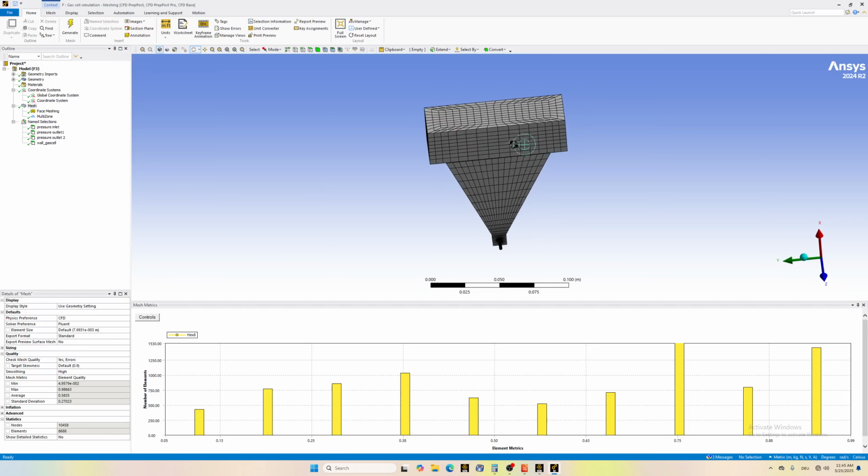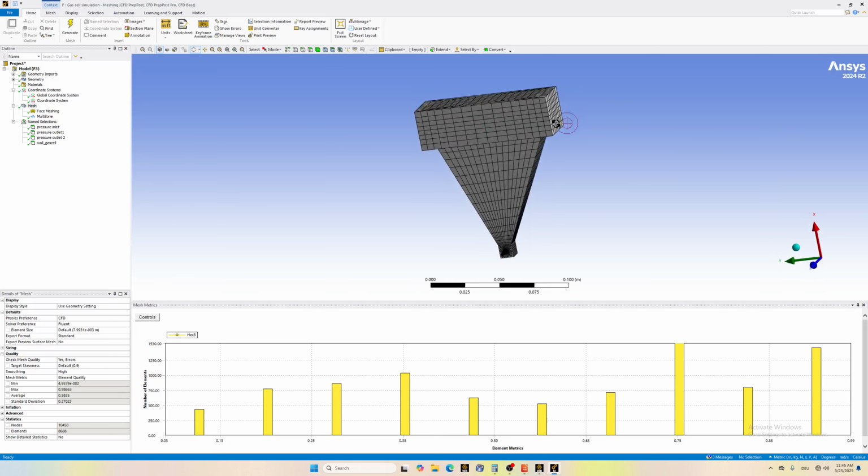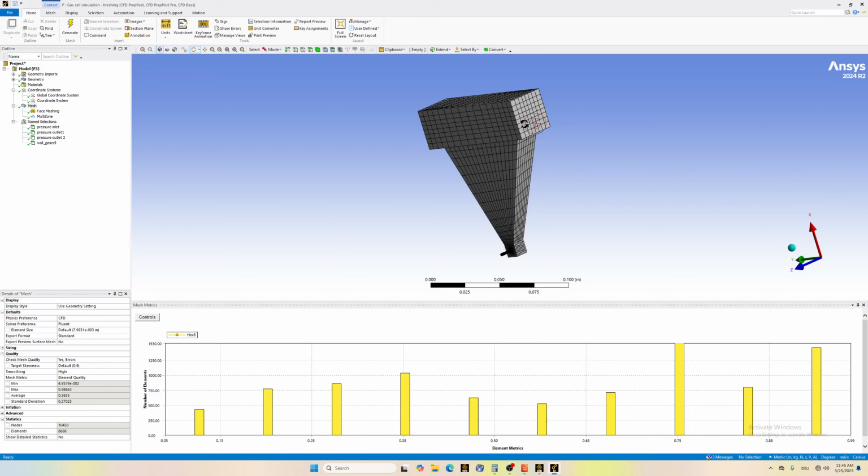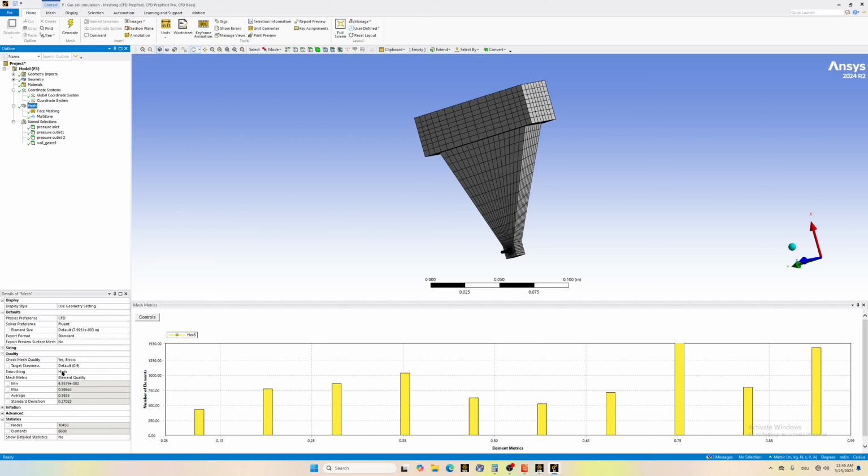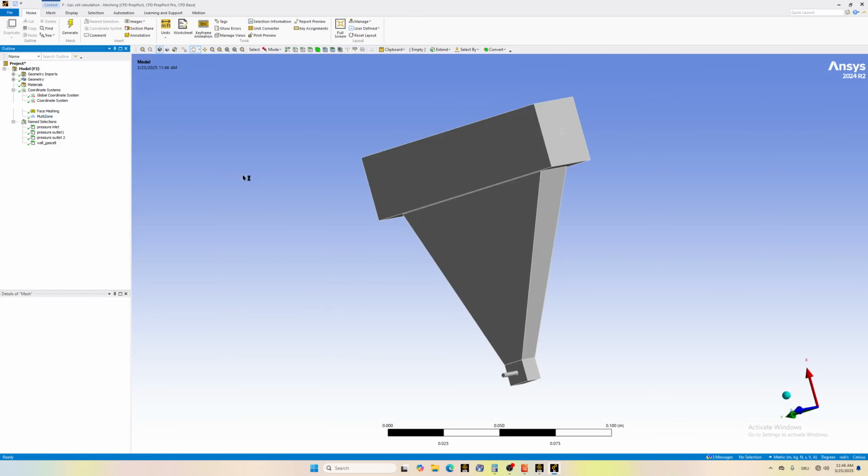Don't follow somebody, you know, word by word. Improvise. You have nothing to lose. Okay, so this is the gas cell, and here we can see the number of cells, of course, is way too low. So let's change here 0.000, let's say 5, and right click, update.